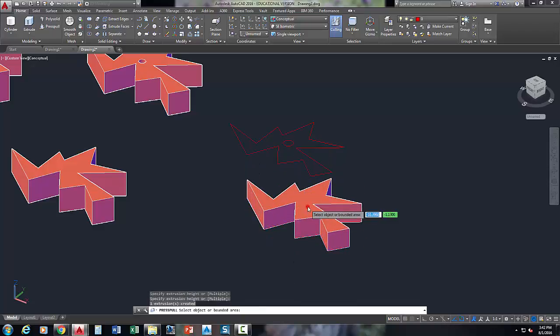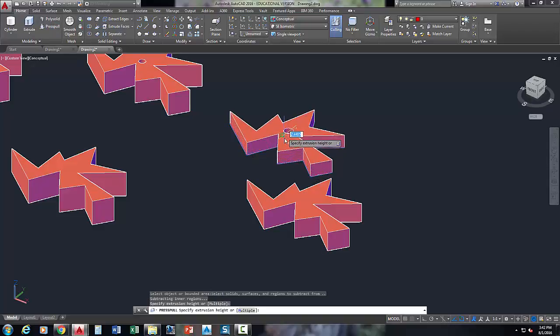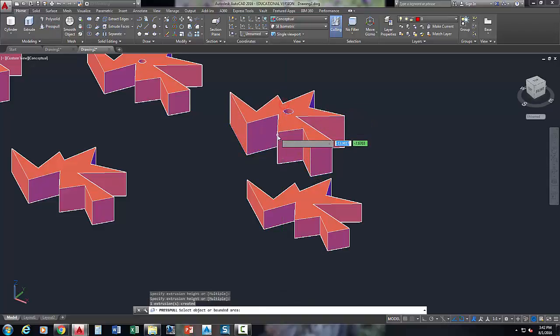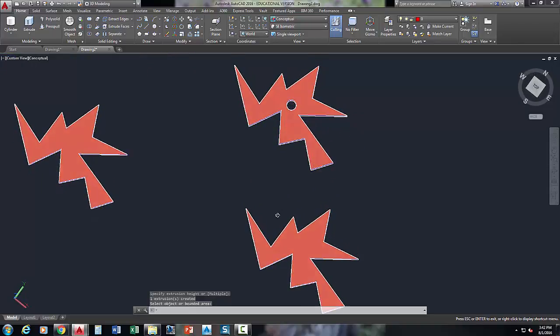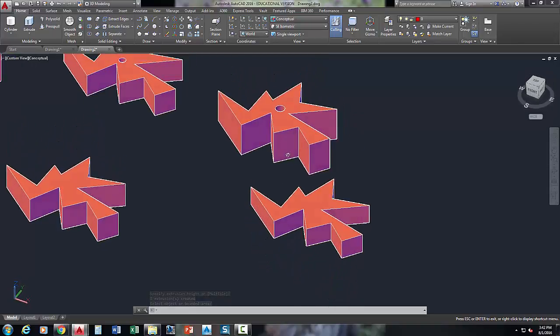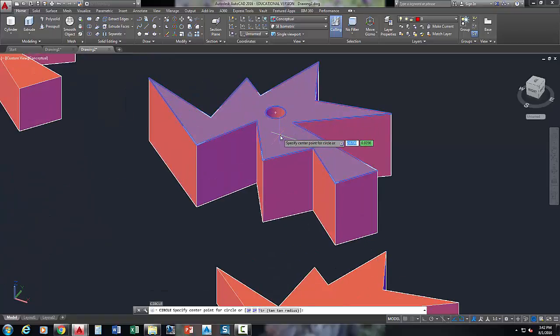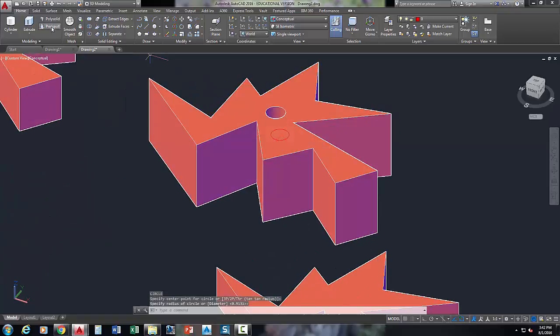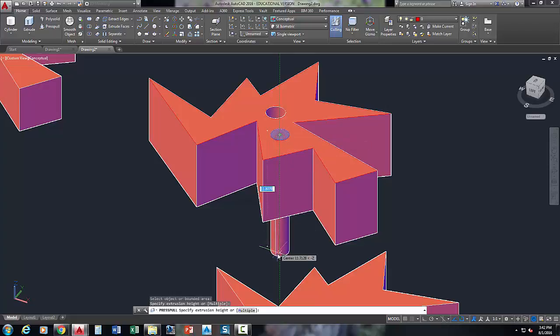And you can just come in here and you can press pull. The cool thing about the press pull command is, since it's finding the boundaries, it found that circle. And so as I'm press pulling this through here, it's automatically extruding that circle and subtracting that circle for me. If I were to draw a circle on the surface right here, and I press pull that, I can either press pull it through to make another hole, or if I were to press pull it up,